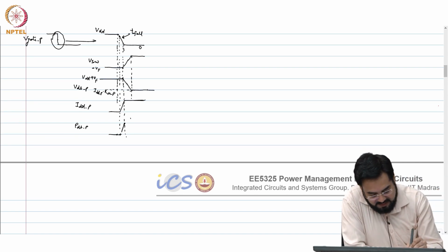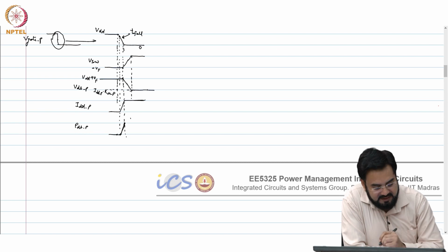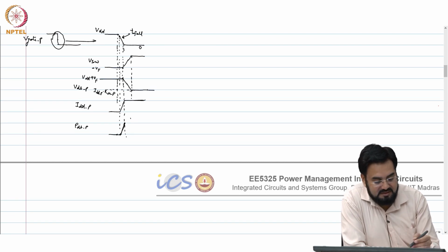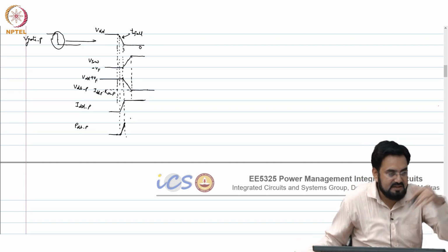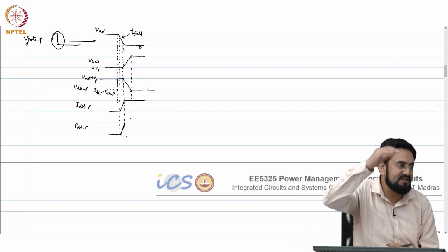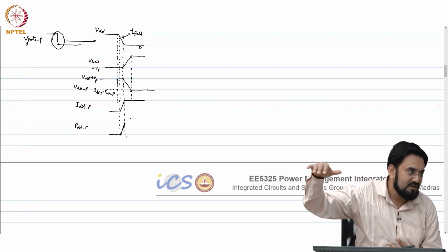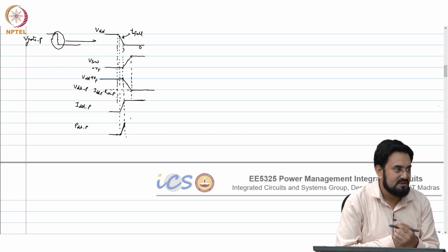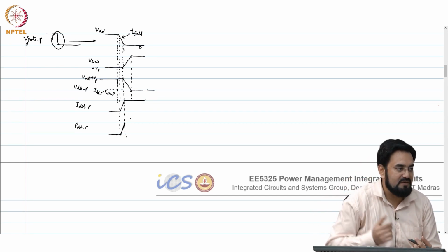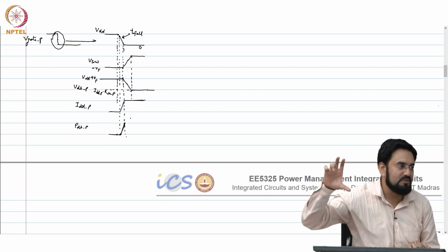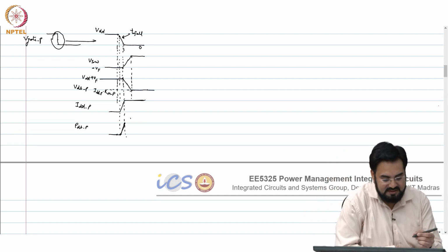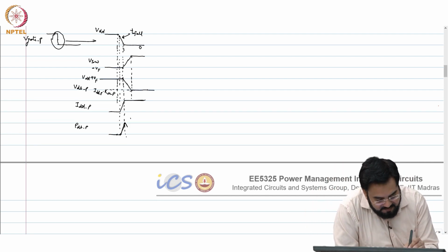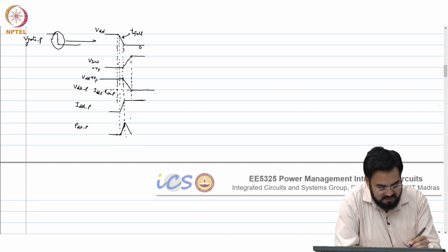So, it will look like a triangle, correct, and then the VDS of your MOSFET starts dropping. So, the power will start again. So, the current is now full, but the voltage is dropping. Earlier the current was 0, but voltage was full, so power was 0. Current is rising, but voltage is maintained. So, at a point you will hit the maximum point and then it will fall.